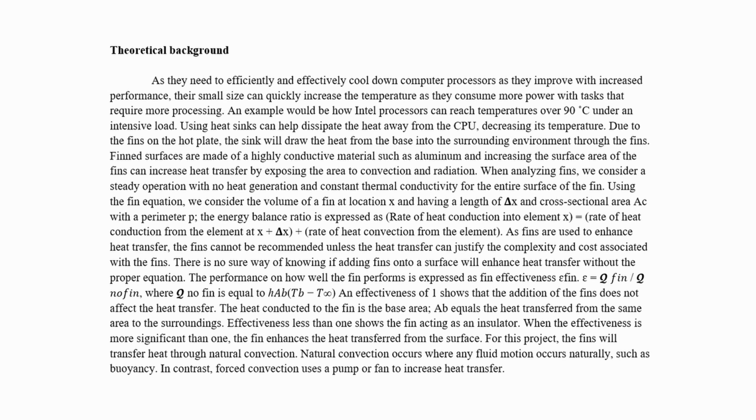When analyzing fins, we consider a steady operation with no heat generation and constant thermal conductivity for the entire surface of the fin. Using the fin equation, we can consider the volume of the fin at location X, having a length of delta X and cross-sectional area Ac with a perimeter of P. The thermal energy balance is expressed as the rate of heat conduction into the element at X, which equals the rate of heat conduction from the element at X plus delta X, plus the rate of heat transfer by convection from the element.